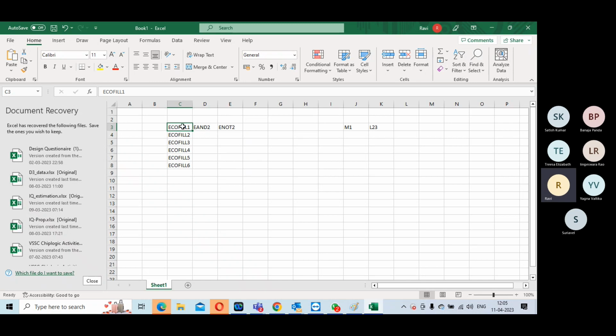You have to understand this, because this is a limitation. That means, if I want to add just one cell, I don't have anything over here because this is not mapped like that. I need a 3 input AND gate, but I only have a 2 input AND gate. That's not mapped to filler. This ECO fill one and only is sitting close by. I don't have a 3 input AND gate. Then what will I do? How do I manage? Either logically we have to construct it, no? 3 input means 2 input over here, add one more like that.